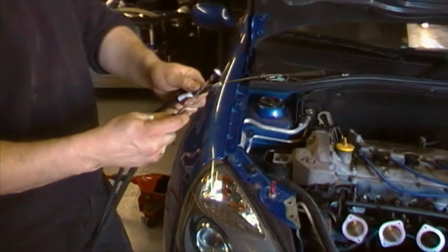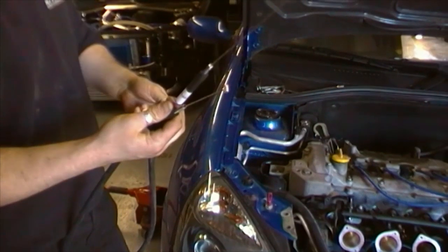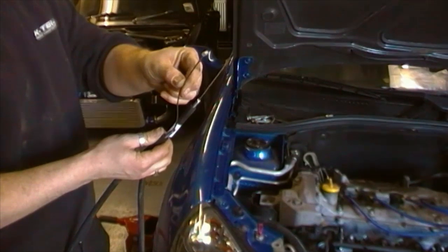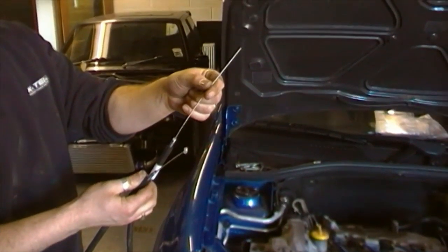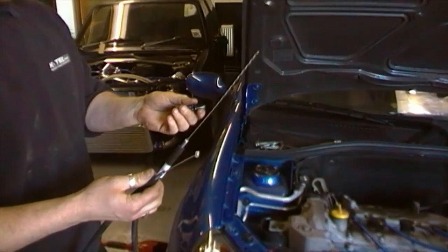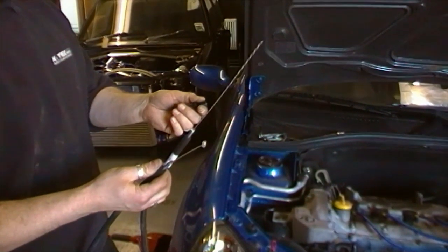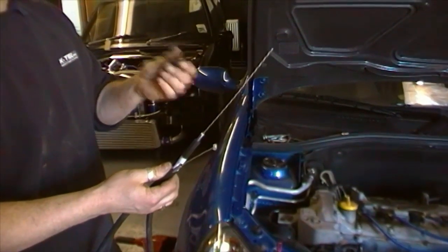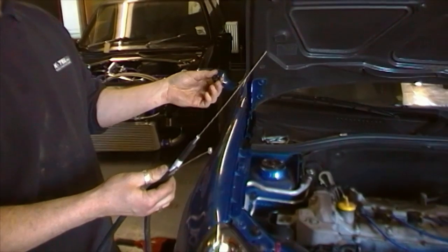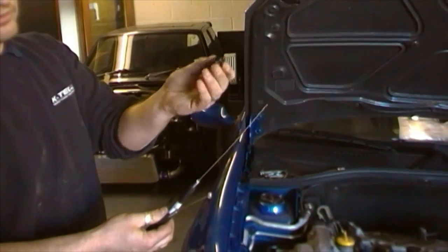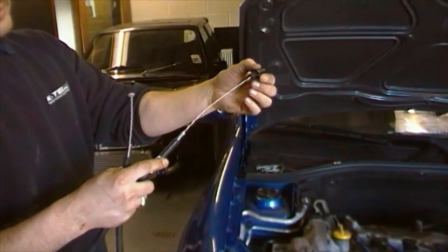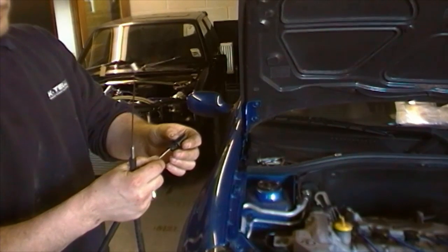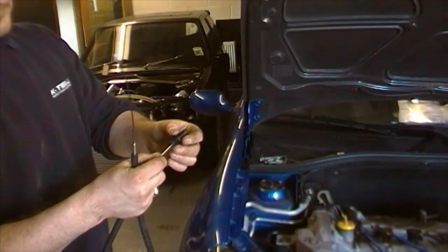Next we need to talk about the throttle cable assembly. This is how the cable will come. This is the end which goes on to the throttle body, and this end goes into the car for the pedal. Now, what you'll need to do initially is remove a rubber grommet from the bulkhead and replace it with a shouldered rubber sleeve, and the shoulder goes on the outside of the bulkhead, in other words engine side. Then this goes through that, and this then allows the cable to sit neatly.